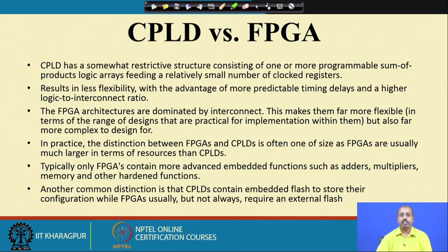Whereas, in many FPGAs you will find that they require an external flash. So, whenever you power on the FPGA chip or you give a reset, it will load the program from the external flash into an internal RAM, and then it will start operating in that fashion.